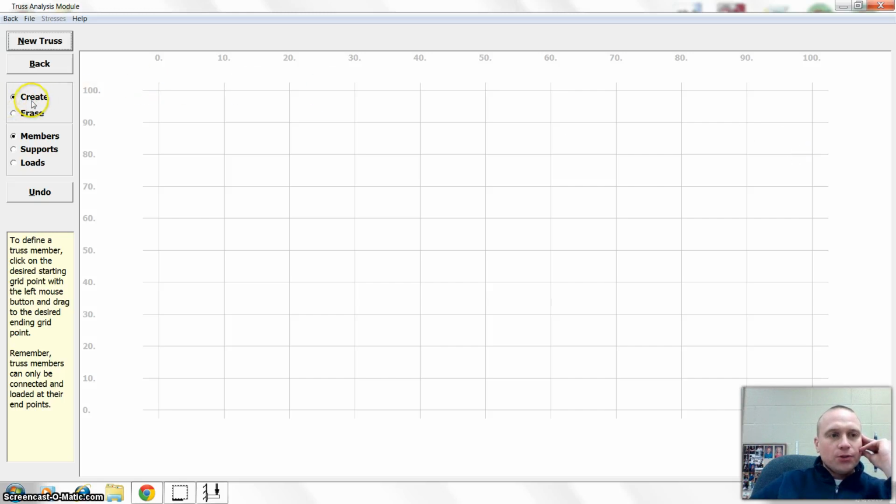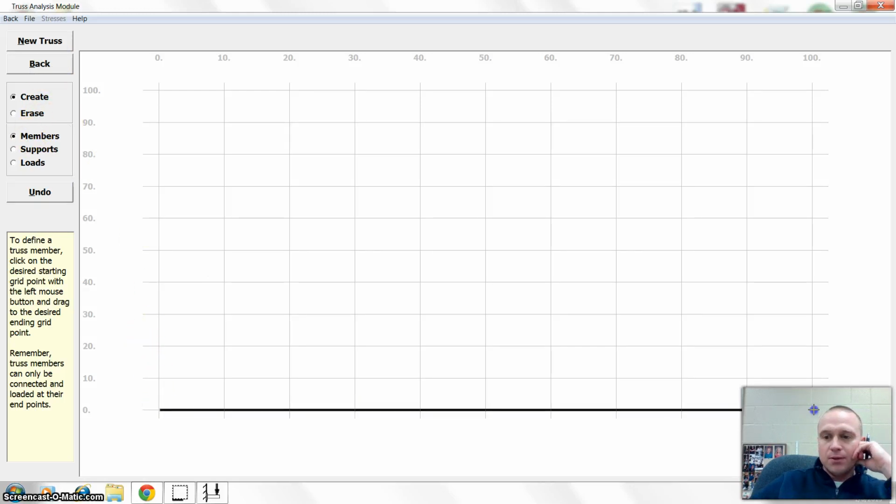The first thing you're going to want to do is create the members. And so I'm going to click and drag a member clear across here, right like that. A common problem that people have with MD Solids is they want to make their system so that it will add a member in. Like let's say they wanted to draw a line down here. They want to add a joint right there. That's not how this works. You have to draw the individual members first. So I'm going to go ahead and do that.